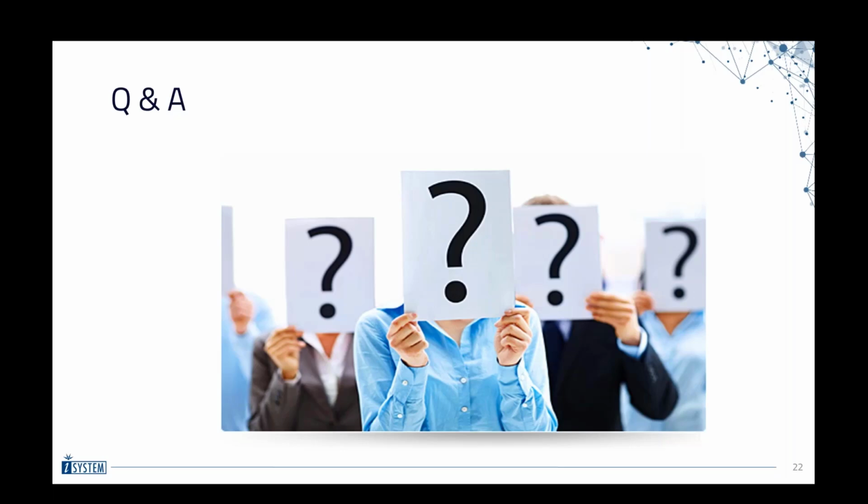Let's go for a last question. Do the DWT comparators also allow to enable data trace for a specific address range, for example, covering an entire data array? So it's a bit of a tricky question. My answer is no, not really, because the comparators on Cortex-M4 can only compare against a single address. So you cannot exactly cover the entire data array, but we do have an option.